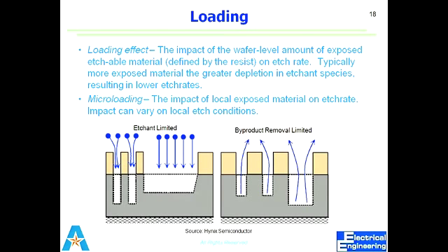actually this film is etched away, that is removed from that part as well. If it's staying there, the etchant would not get into there, and the etch rate would be different at that part if it's in trenches or in small feature sizes. So that's why we always keep moving it a little bit so that the byproducts are removed from that area and fresh etchant comes in contact with the film. Okay, so that we call byproduct removal limited. So this is a loading effect.